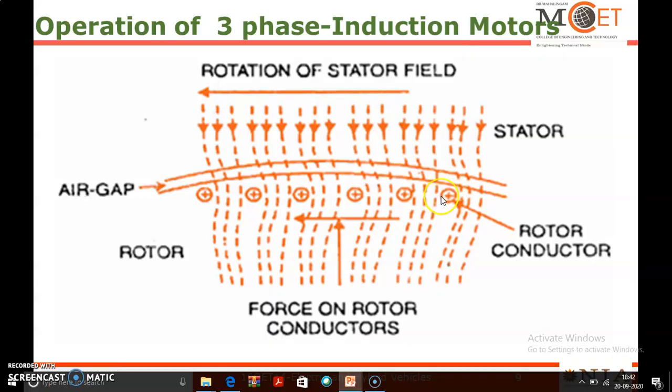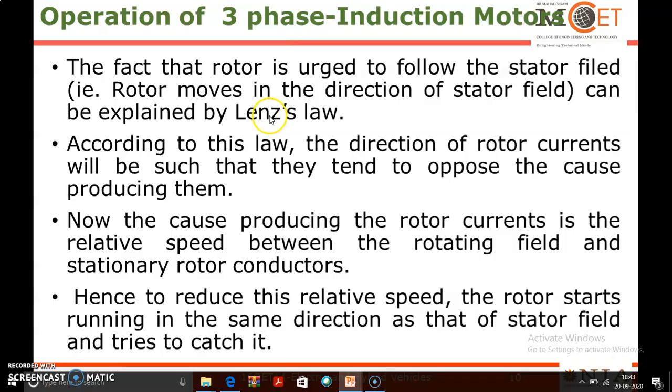So this rotor MMF, that is the rotor magnetic field, and the rotating magnetic field produced by the stator interact with each other, due to which a mechanical force or torque is developed in the rotor conductor in the same direction as the stator rotating magnetic field. Next.